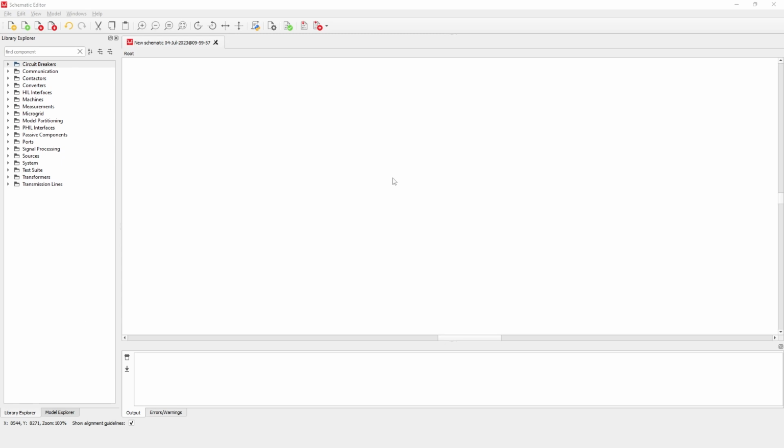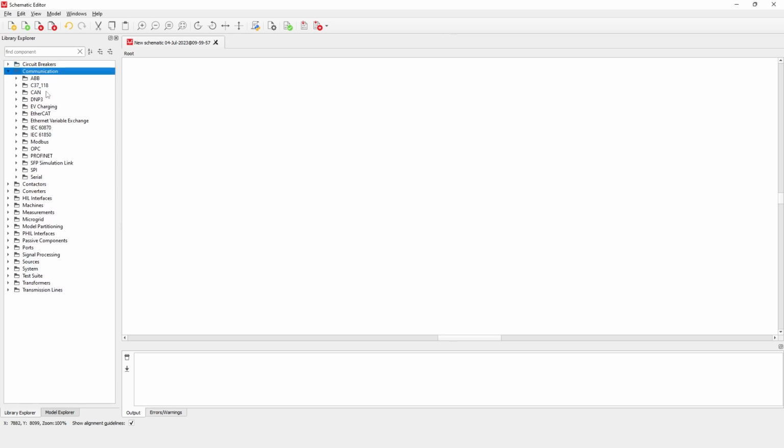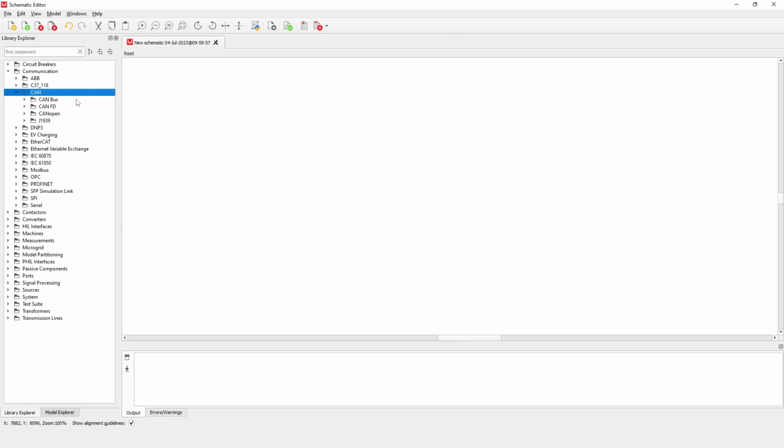The Hill 606 device offers 4 distinct CAN communication channels, as featured in the CAN pinout. CAN 0P and CAN 0N, CAN 1P and CAN 1N, CAN FD 0P, CAN FD 0N, CAN FD 1P and CAN FD 1N. With the 2023.3 software release, you can now use the CAN FD communication channels to set up a regular CAN bus communication.